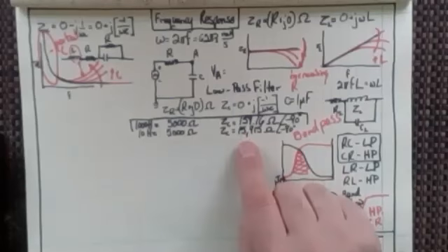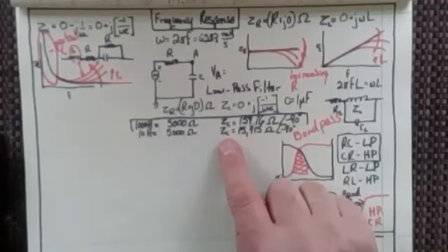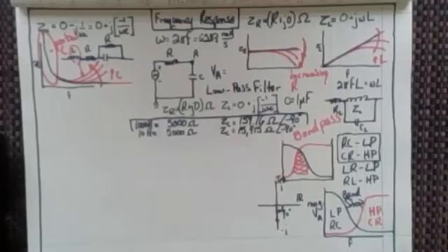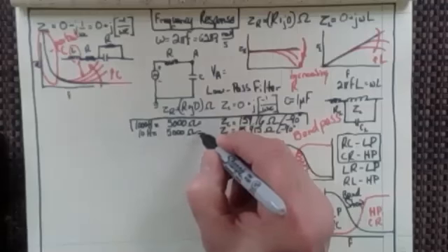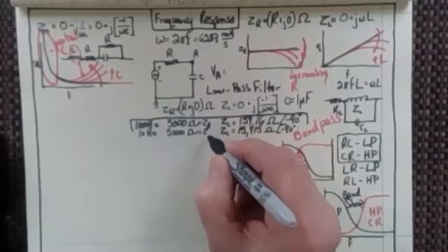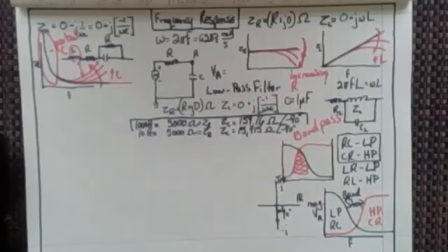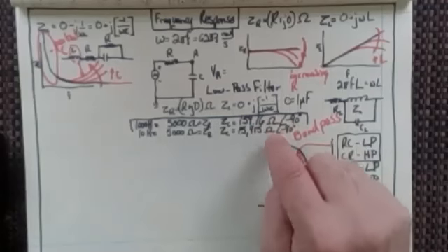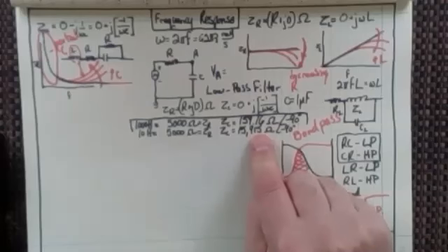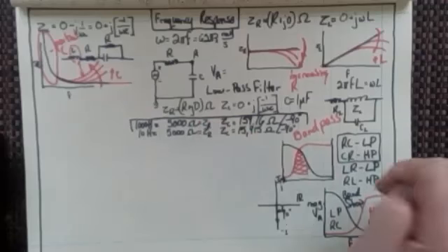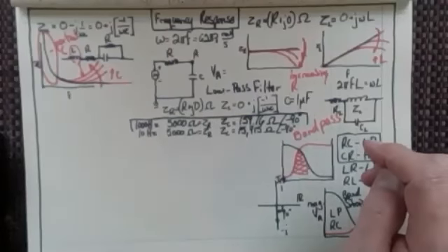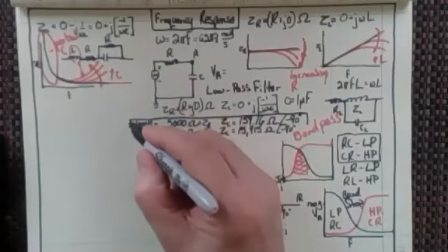So you can see that at the lower frequencies, the capacitive impedance takes over, but at the higher frequencies, because it's 1 over omega C, the resistive part is going to take over. Does everyone see that? At the lower frequencies, I've got a capacitive predominance, but at the higher frequencies, I've got a resistive predominance. That's right, and that's what I wanted to show you.